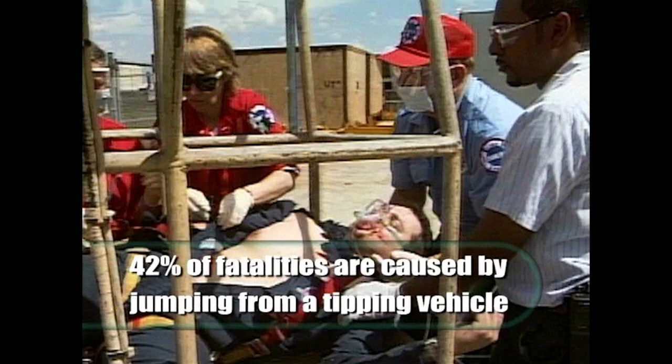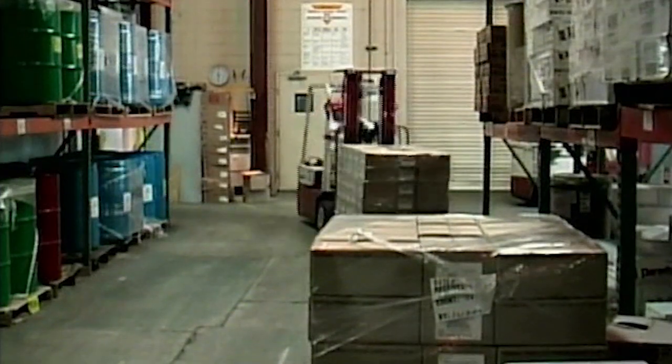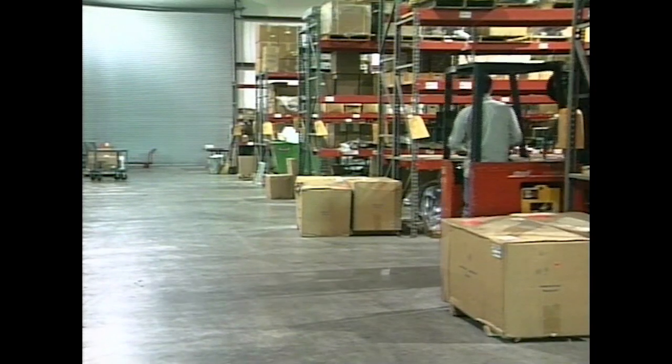42% of forklift fatalities are caused by the operator trying to jump from a tipping vehicle. To keep this from happening to you, always remember to keep the load as low as possible and stay with the vehicle if it tips over. Wearing your seatbelt is the best safety measure.